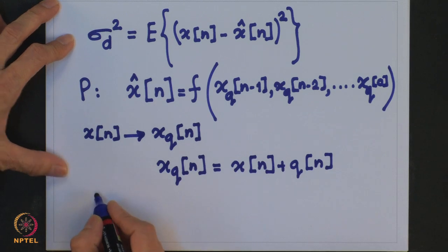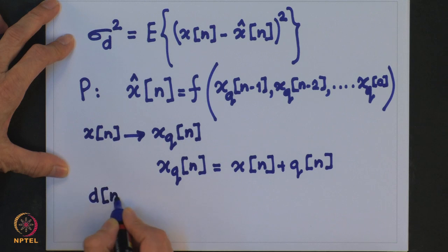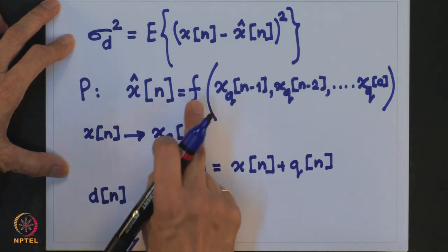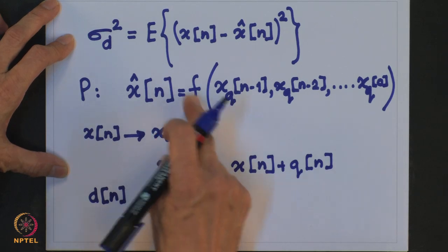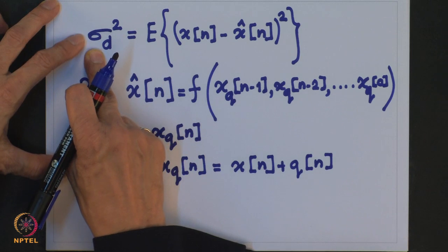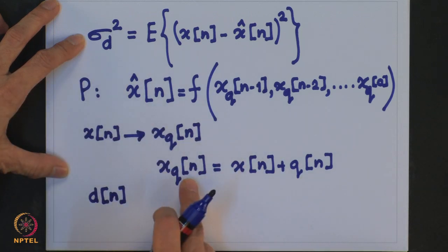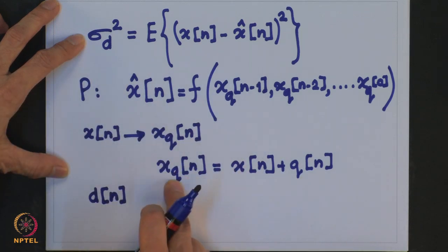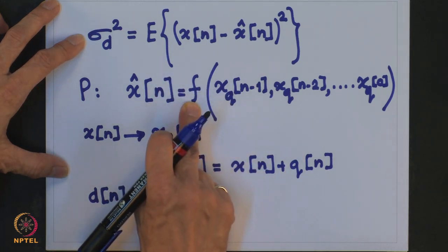So, this quantization noise depends on the variance of the difference sequence. Thus, by picking the function f, we will affect the variance of the difference sequence, which in turn will affect the reconstruction xq, which then affects the selection of f.